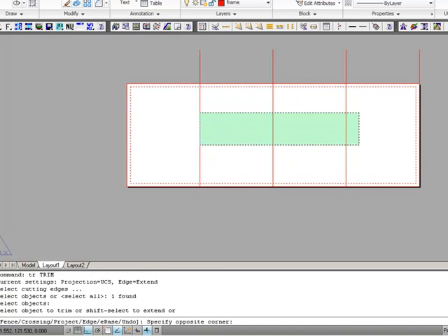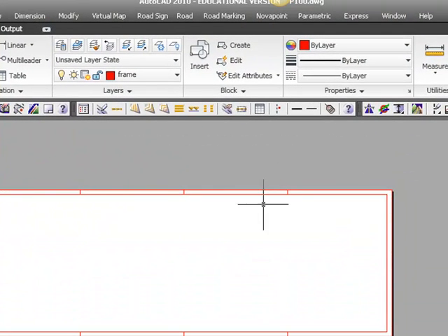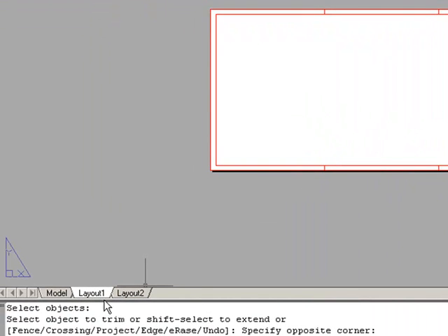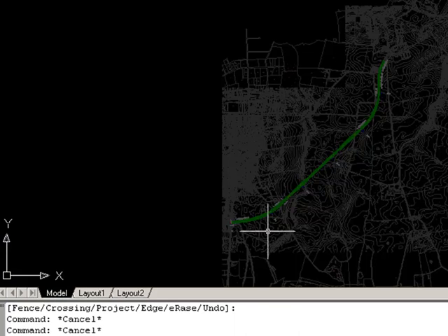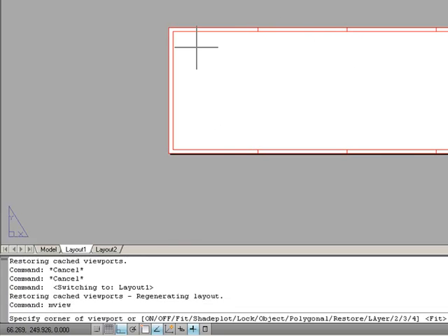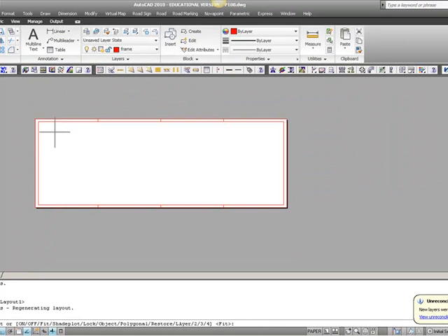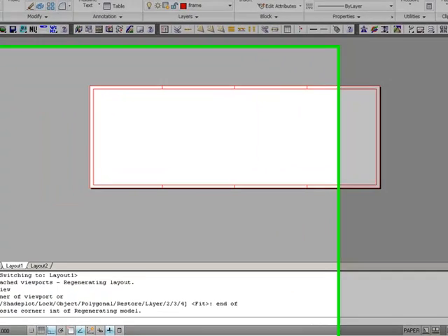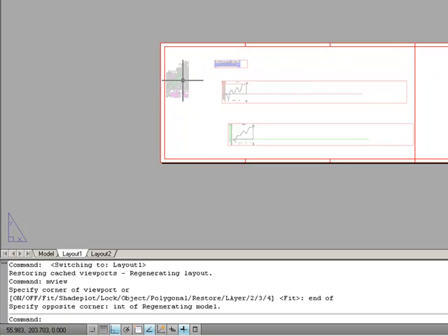And then I will trim. So I have now my marks so that I can fold my drawing. Then I need to get access to the model world. We are in the layout world, and it's in here, my model world, where I have my drawing. So from layout I need to make what we call an M view. That's an opening in this drawing, kind of a window into model world. And I will create a window ranging these 3 A4s in width, leaving one page for drawing information. I have now a window to my model world.